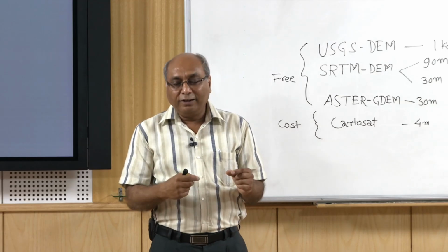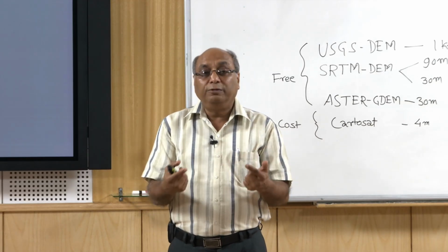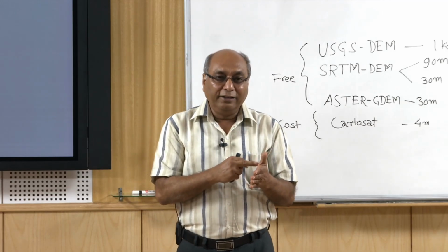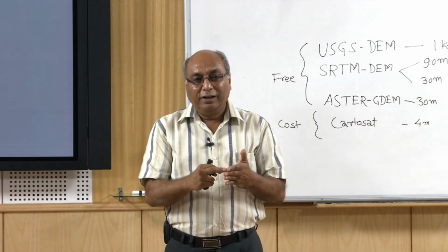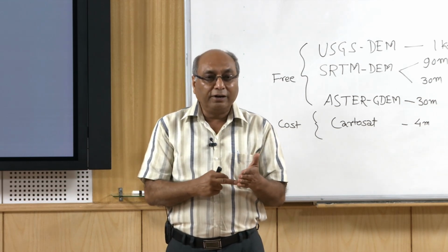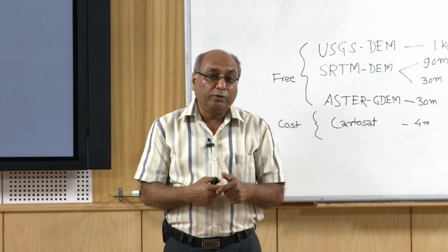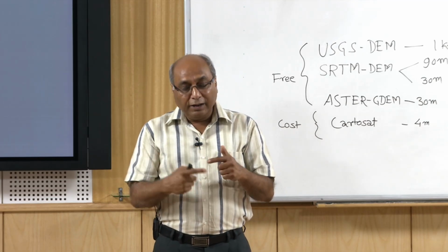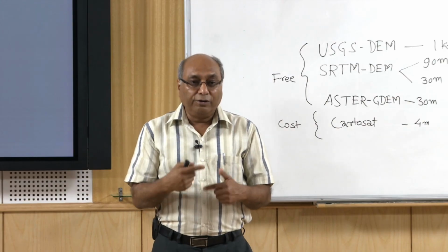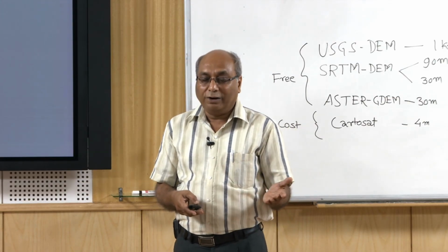In the case of high spatial resolution data, the swath width might be even 11 kilometers, compared to NOAA data at 2800 kilometers. With high resolution data, maybe 1 meter resolution, the swath width may be 121 kilometers. So the repeat cycle, or temporal resolution, is going to be relatively very low when we compare with the NOAA data.